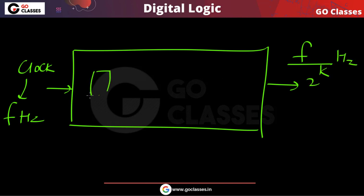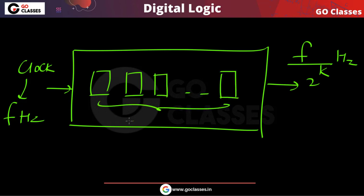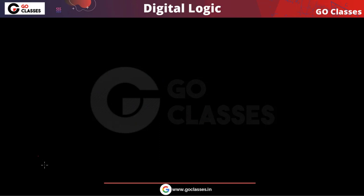Very simple, you connect k T flip-flops. So how many T flip-flops? Total k T flip-flops you can connect, like this. The output of one flip-flop will be acting as clock for the next flip-flop, and this will work. So this is the basic idea. Like this you can do the frequency division by 2 power k. I hope this point is clear.